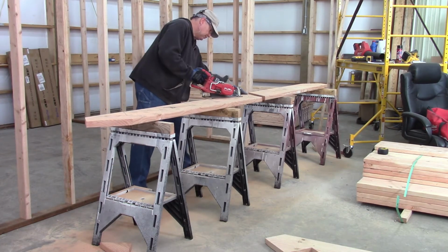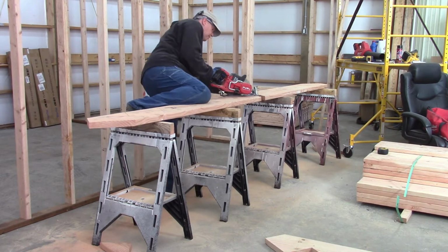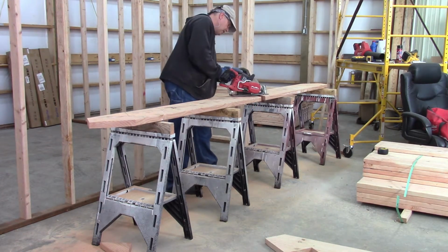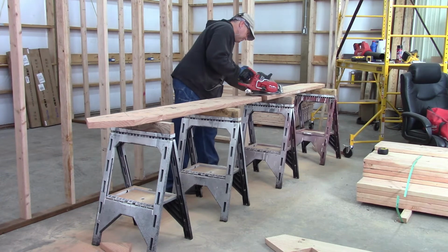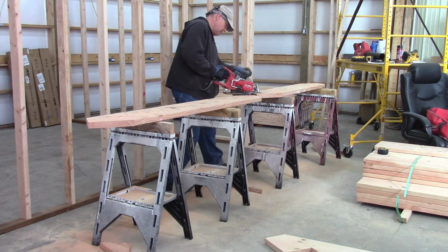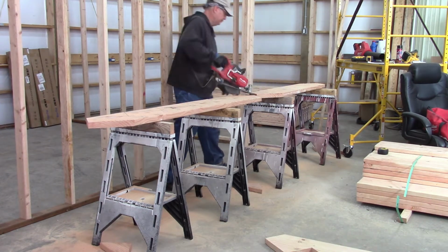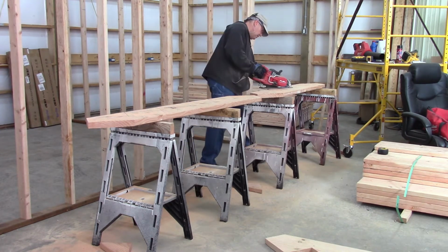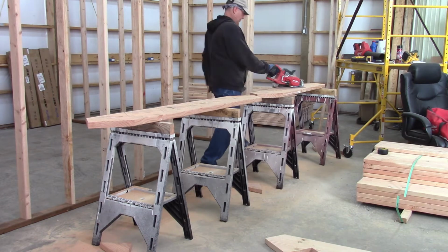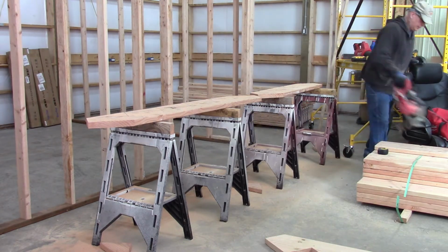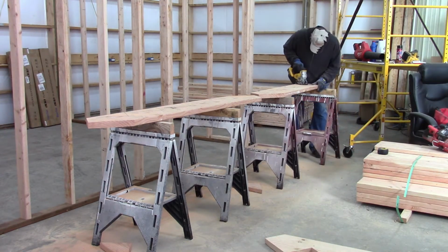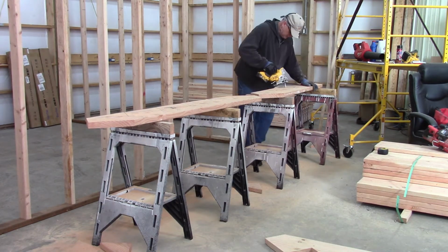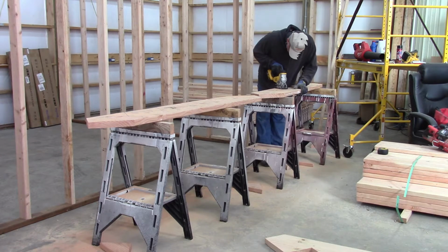Another thing to keep in mind is that the bottom step always has to be an inch and a half shorter than the others for the rise, because you're coming from the floor up to your first step, and the tread of course is 1.5 inch thick. Otherwise the first step will be taller than all the others. This way they all come out to exactly the same amount.